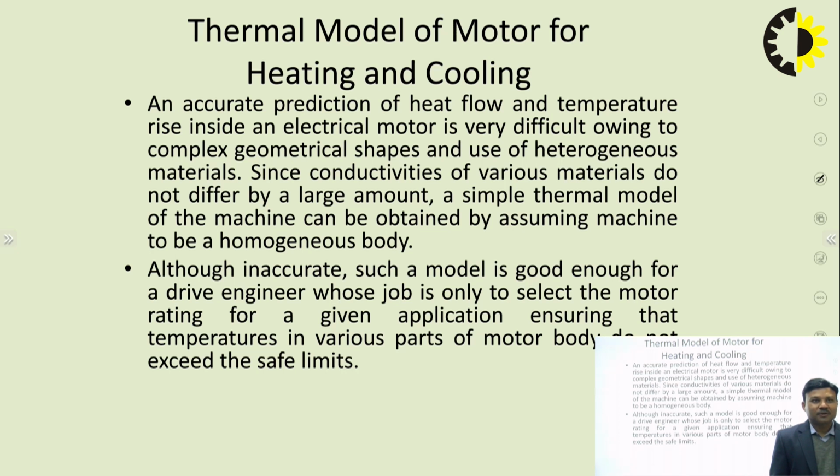So this is the objective of selection of motor power rating. Now let us see the thermal model of motor for heating and cooling. An accurate prediction of heat flow and temperature rise inside an electrical motor is very difficult owing to complex geometrical shapes and use of heterogeneous material. Since conductivities of various materials do not differ by a large amount, a simple thermal model of machine can be obtained by assuming the machine to be a homogeneous body. Although inaccurate, such a model is good enough for a drive engineer whose job is only to select the motor rating for a given application, ensuring that temperatures in various parts of the motor body do not exceed the safe limit.